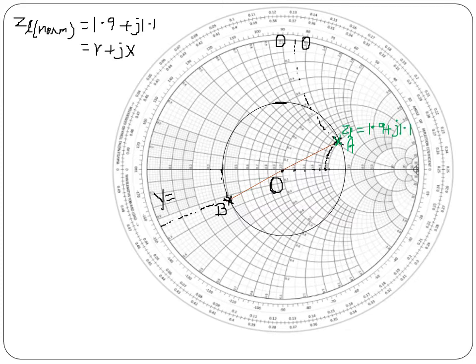This is point 3, it's point 4, therefore the R circle is 0.39. Minus j, 0.2, 0.3, and it's 0.22, and it's 0.24, and in between 0.22 and 0.24 the X circle is 0.23.